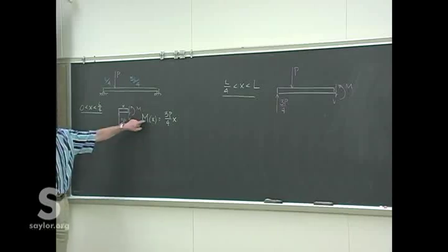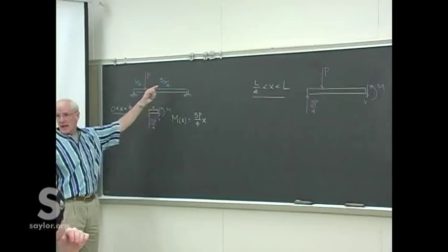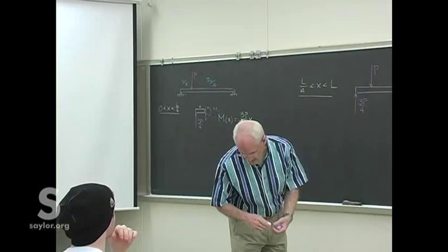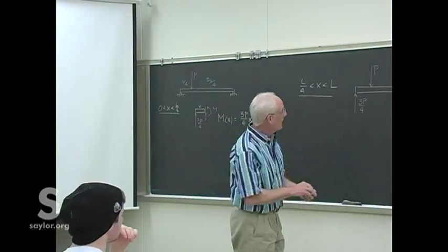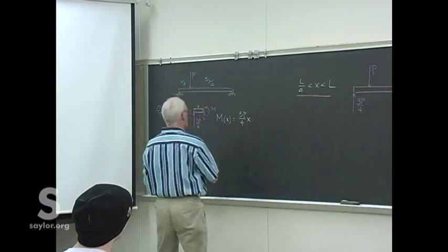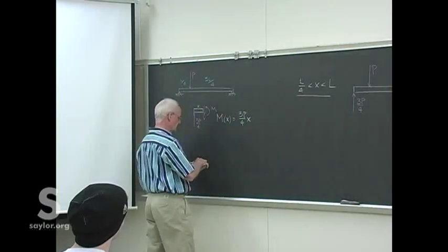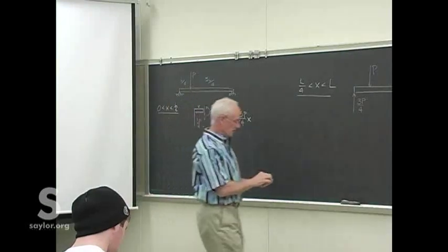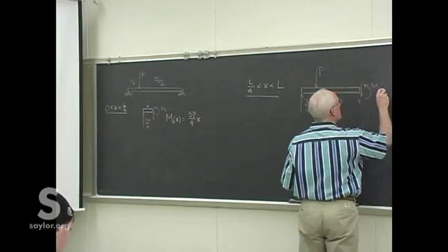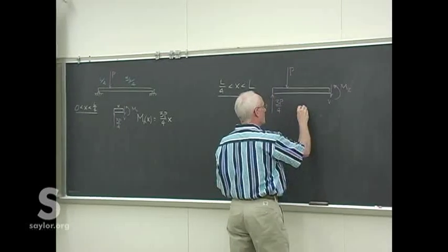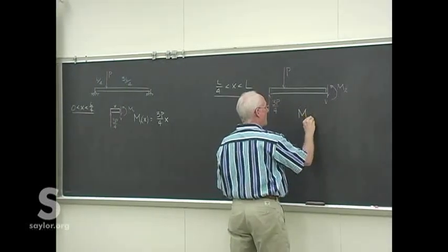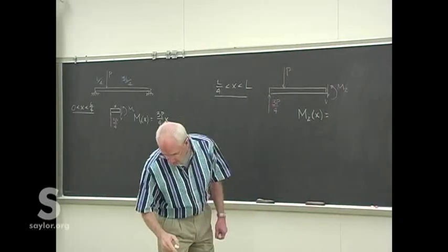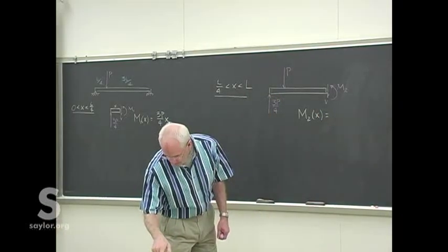So, start with that, integrate back twice to get the load curve, the deflection curve, the elastic curve. And let's call this M1, because we're going to have two of these M's, since we have two sides of the beam. So this will be M2. And just figuring out what that moment should be.